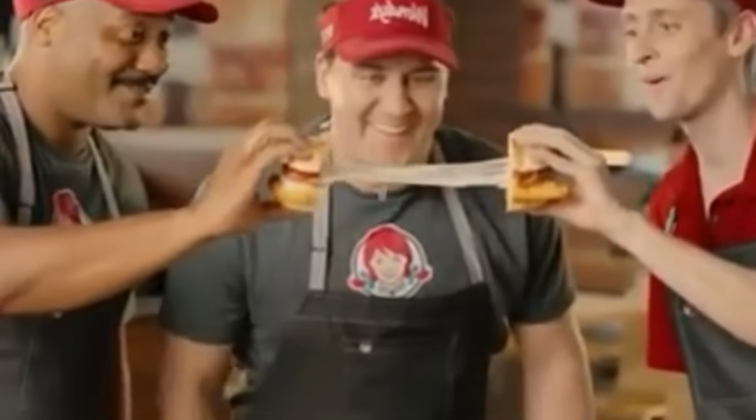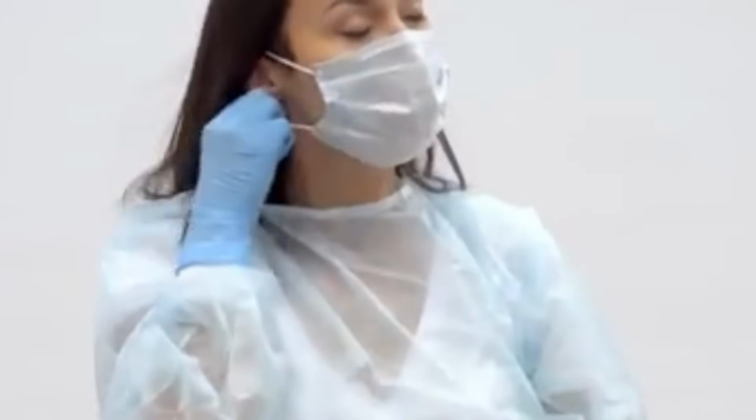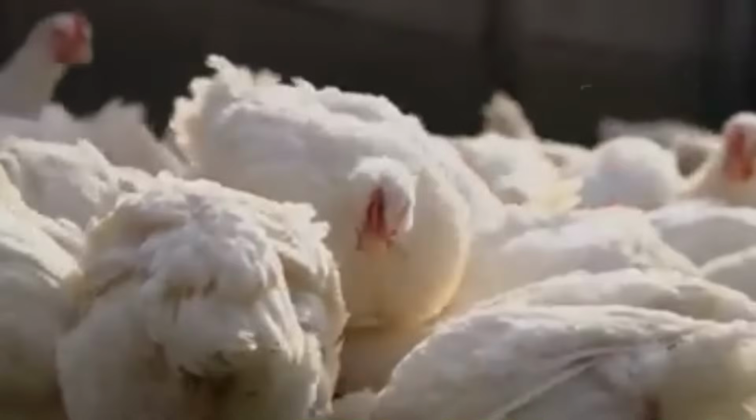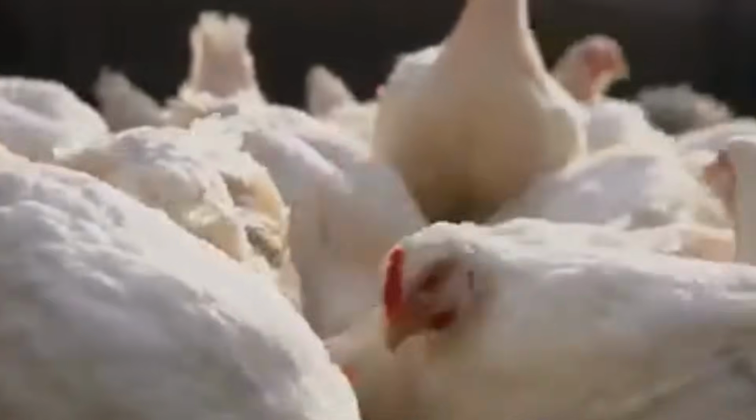Wendy's burgers begin with raw ground beef held in refrigerated stainless steel bins, fitted with auger-driven dispensers. The beef is pre-ground to a fixed particle size and loaded into a hopper positioned above the patty forming system. The patty forming machine uses a hydraulic ram to compress a measured quantity of beef into a square mold.